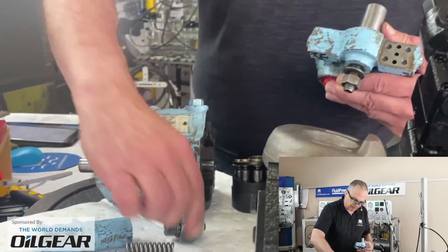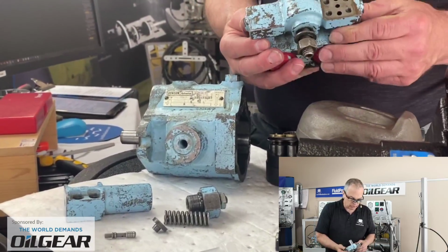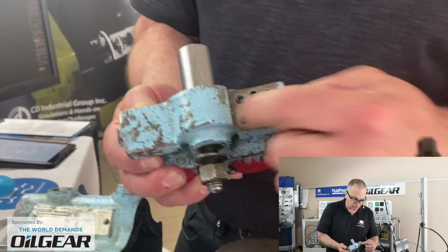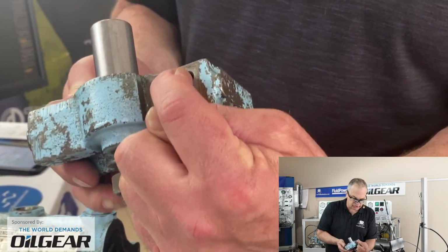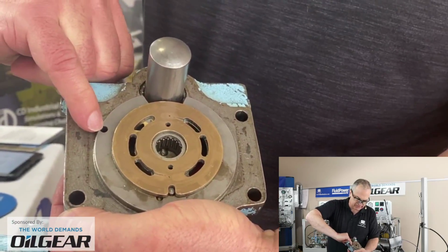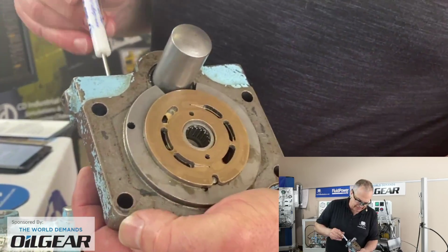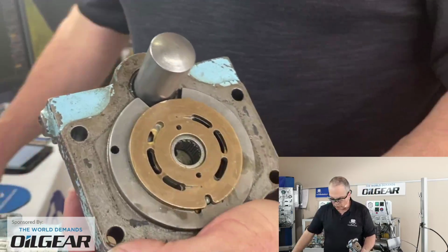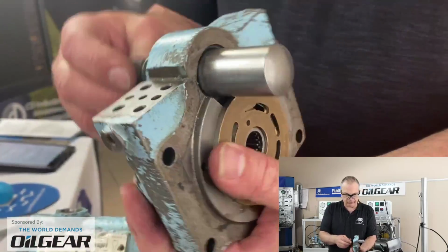There's our adjustment, which I removed earlier. And then the controller exhaust on the compensator spool drops down through the hole closest to the connection between the cap and the case, draining inside the case through that passage right there. If I stuck my screwdriver down in there, you'd see it in that little hole, or you could squirt fluid through it with one of our syringes. So that's some basic activity.